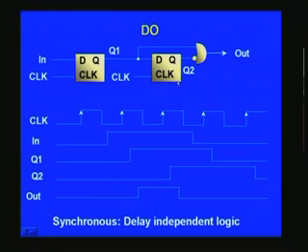So, ultimately we get a pulse like this, and you notice that the actual width of this pulse is the width of the clock period, except that there is a delay owing to the delay between clock and Q, because internally there are circuits and any gate means delay. That is what is getting reflected here finally, and this is how we solve for a single pulse if you desire just a single pulse to be created.